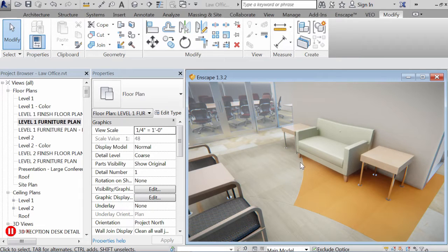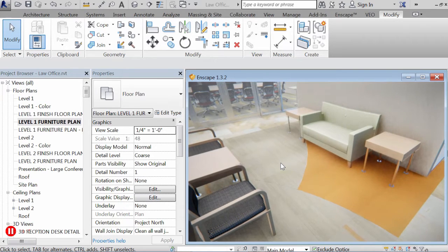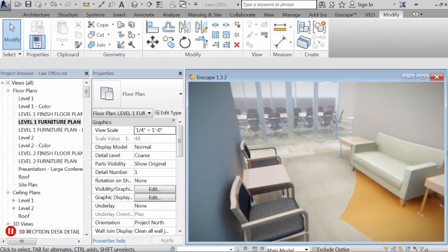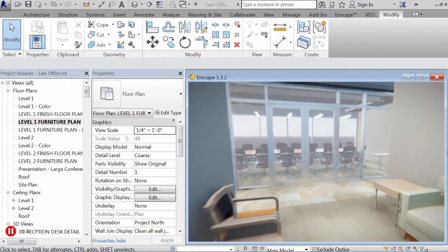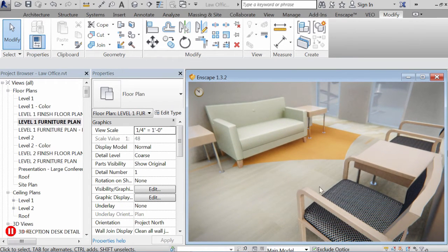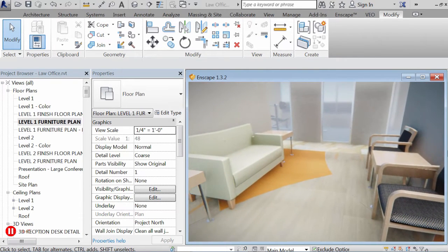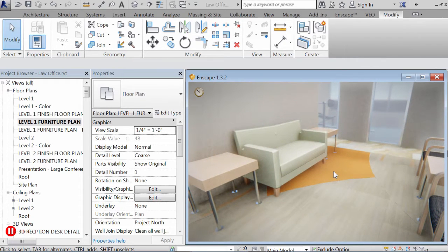Yeah, so that's one of the things I cover in the interior design class that I've done. I've presented this class now already a couple of times in DC at RTC and Singapore. And the issue is that the structural floor is usually coming in as a link from the structural model. And we don't really have the opportunity to edit that material. And because each room has a different material, we can't use split face and paint because it's a linked floor. So what we typically do, and what I advocate here in the book, is creating an 1/8 inch thick floor that's offset up 1/8 inch.